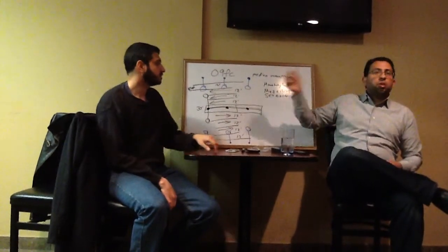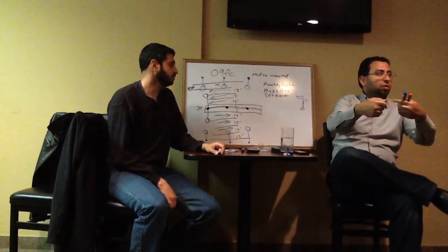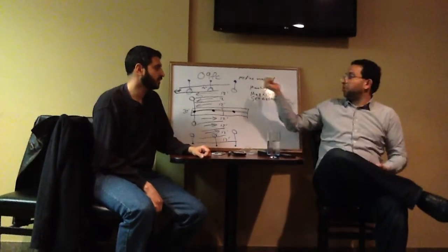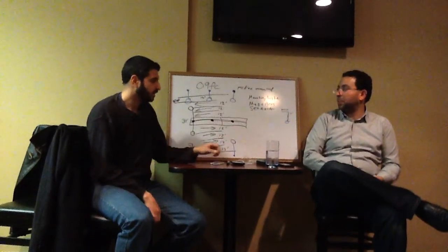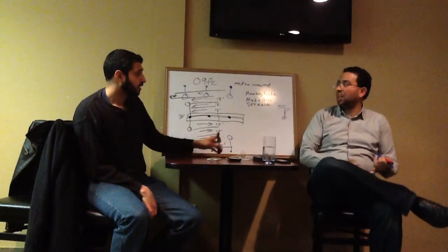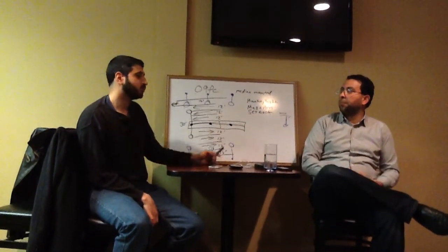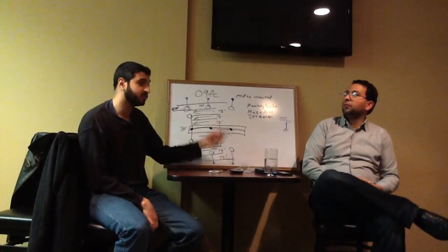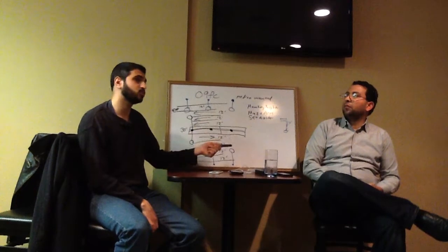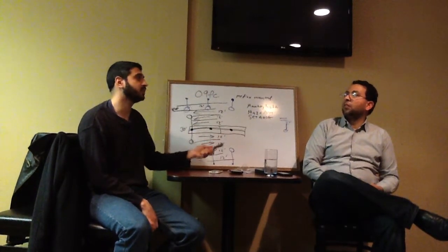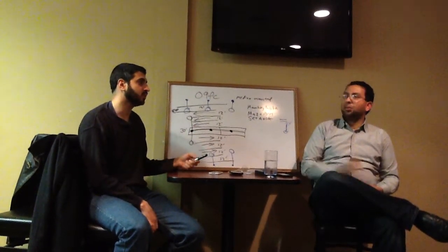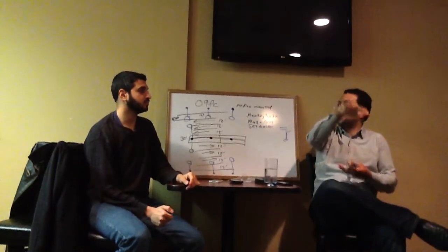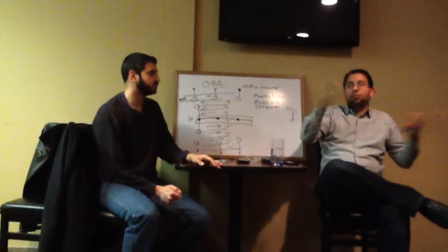FYI, most of this information will be given to you. When we tell you to do the design for this roadway, you will be given that information. Sometimes, if the pole is existing, you can go out and measure. But if you're doing the design from scratch, then it's up to you to decide what the pole height is going to be to get the mounting height that you need. But most of the time it's existing, so you have to live with it.